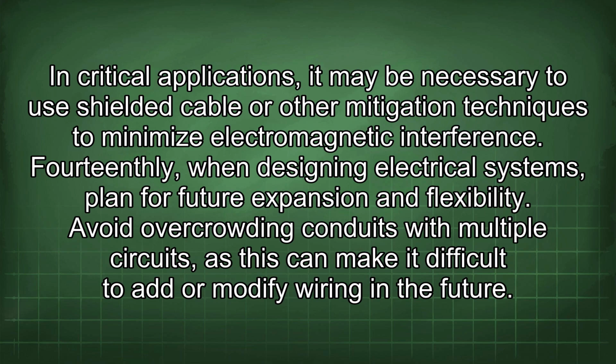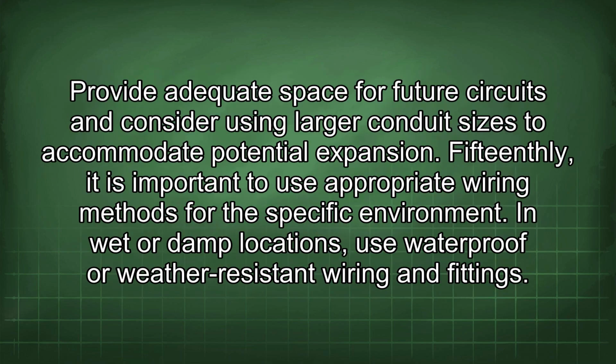Avoid overcrowding conduits with multiple circuits, as this can make it difficult to add or modify wiring in the future. Provide adequate space for future circuits and consider using larger conduit sizes to accommodate potential expansion.